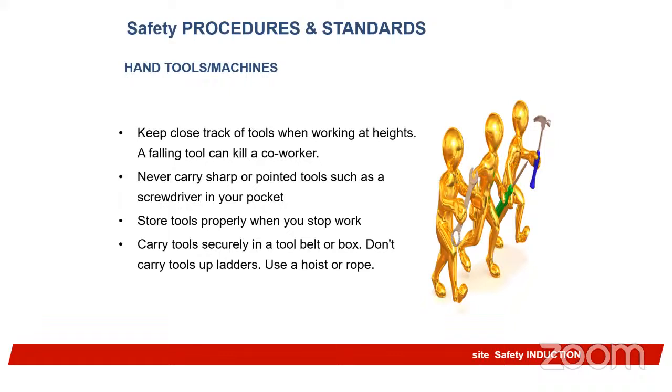Never carry sharp or pointed tools such as a screwdriver in your pocket. Even nails, some will put nails in their pocket or in their mouth. We've seen that on construction sites. They'll put nails in their mouth, especially carpenters. Then we tell them, okay, the minimum we can do is to have something like these PET bottles for water, put your nails in there and maybe tie it on your neck. It's not safe for you to put nails in your mouth.